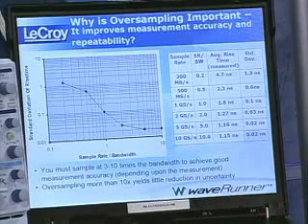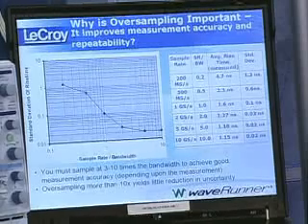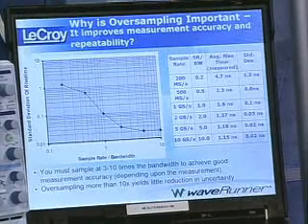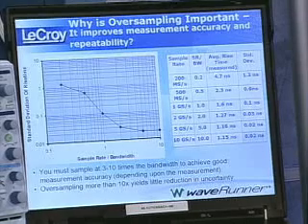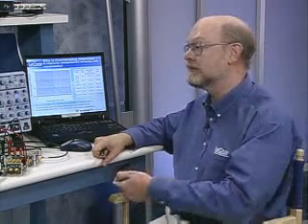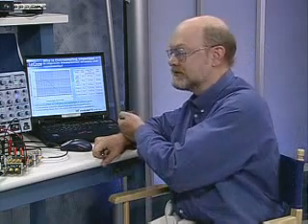So this would be why even your 350 megahertz bandwidth scope has gigasamples. Exactly. It has a 2.5 gigasample ADC. So the ratio of the ADC sampling rate to the bandwidth is good. That's critical for us because we publish this. It goes into a legal document, our data sheet. Right, so there's no question about the quality of our measurements. If you want to characterize a part, you want to know for sure that the numbers you're putting down there are right, whether that's a published data sheet or something that you merely give to your boss and say, boss, here's the part that we've made. So you want to have confidence in your measurements.